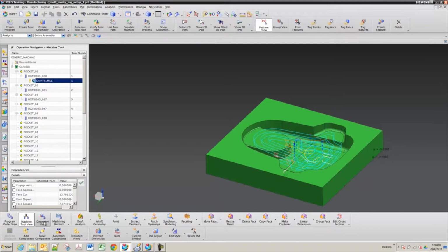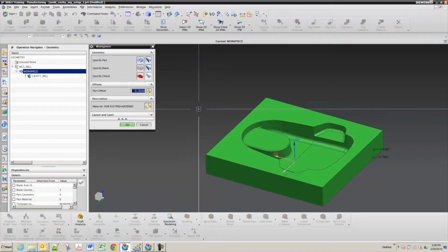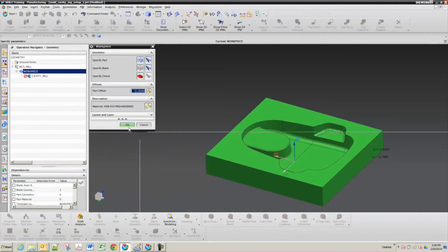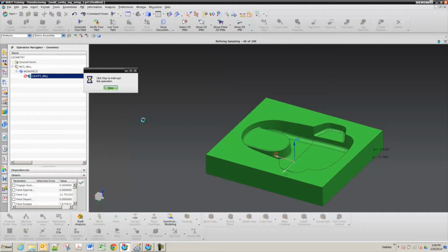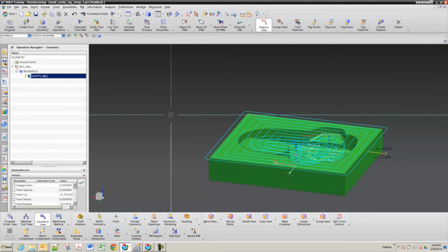Okay, so go to geometry view, edit your workpiece. Yeah, it knows what it's doing. So change the ZM plus to 50 thou. It's smart. It says, well, you asked me to leave 20 and there's only 15. Yeah, that's the top now.